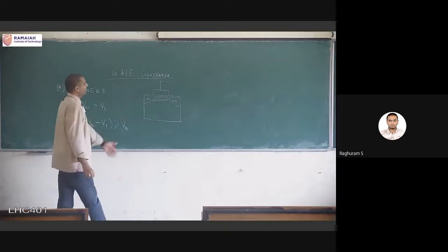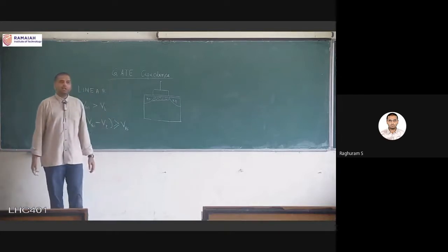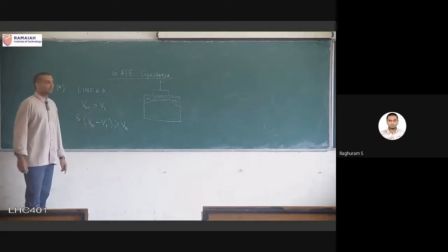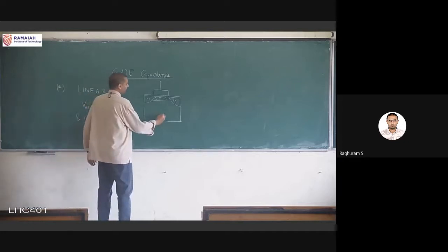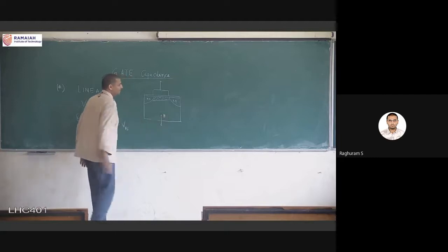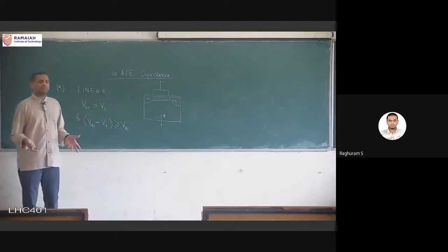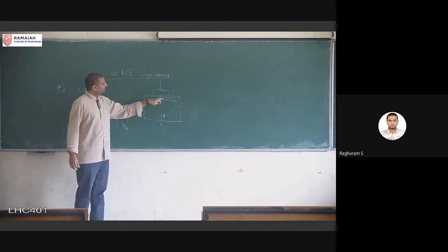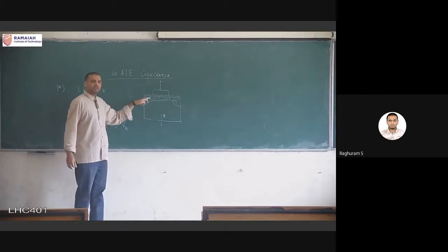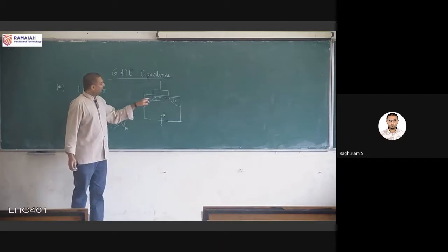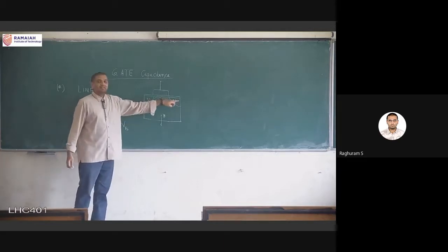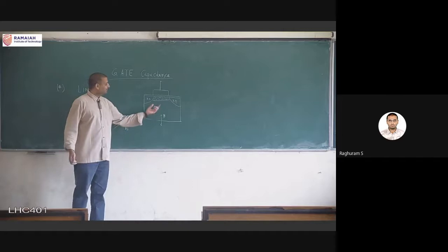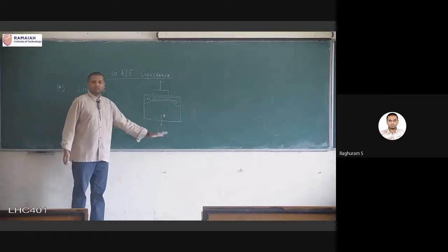So it's a very nice picture, because now directly we can visualize the parallel plates of the capacitor. In linear mode of operation, what happens is, this bulk terminal is completely out of the picture. The parallel plate capacitor, one plate is still the gate, that is always true, but the other plate this time is this inversion region which is connecting the source and the drain terminal, and this whole thing forms the other plate of the capacitor, and the bulk region is completely out of the picture. The bulk is hidden from the capacitor, it is not part of the equation.